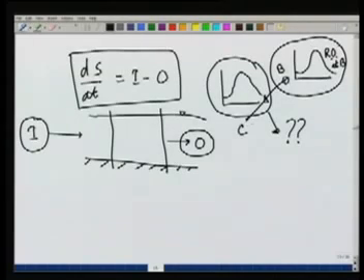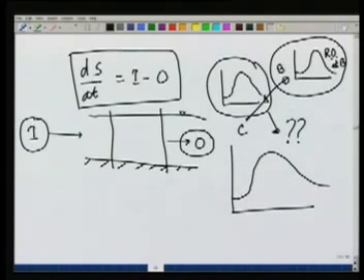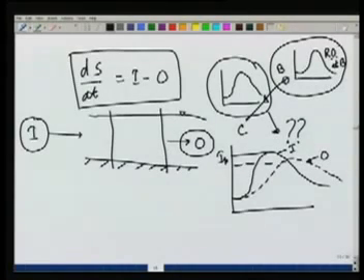How will the outflow at point C look because of this flow at B moving through the channel and reaching point C? Because when the flow is routed through the channel, it will not retain its shape. If the inflow hydrograph is like this, the outflow hydrograph may look like this. I, O. So here we are indicating O for outflow, I for inflow. Inflow will have some peak and the outflow will generally have a smaller peak, OP.